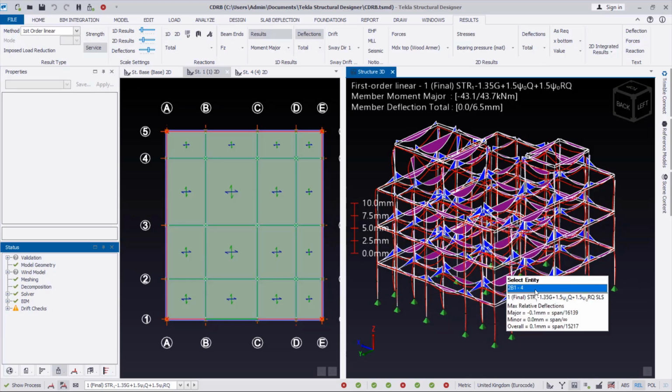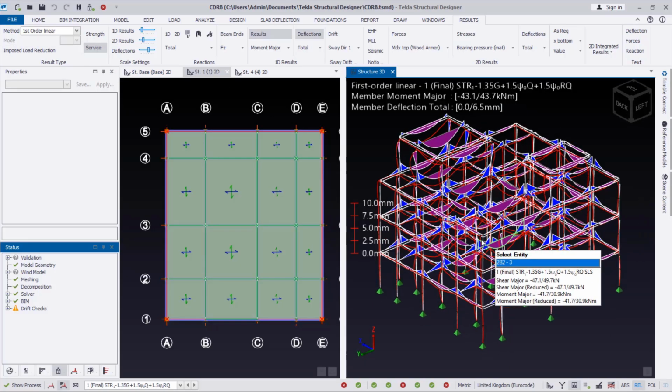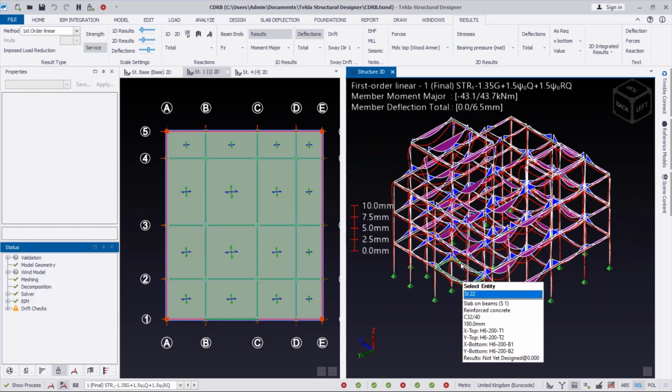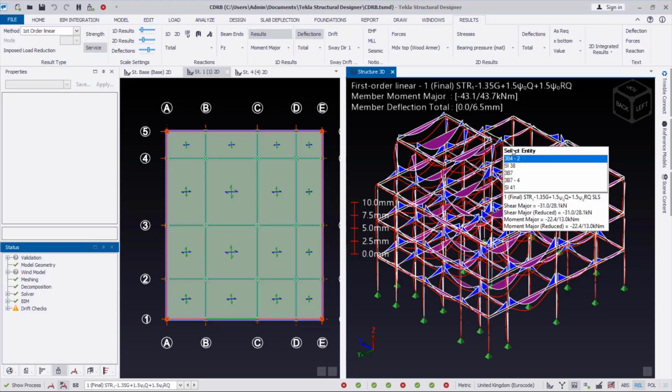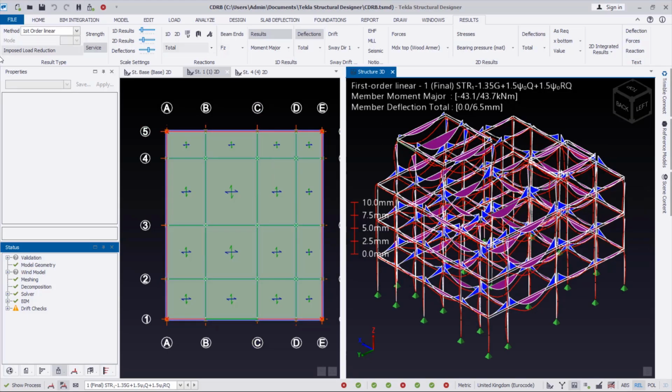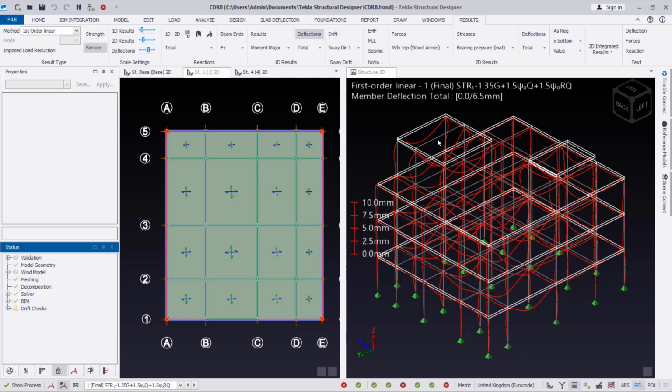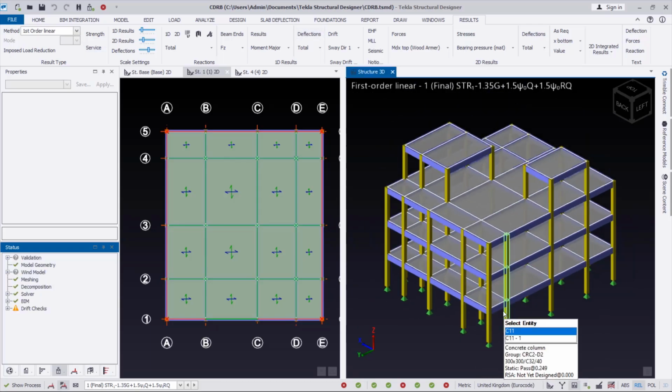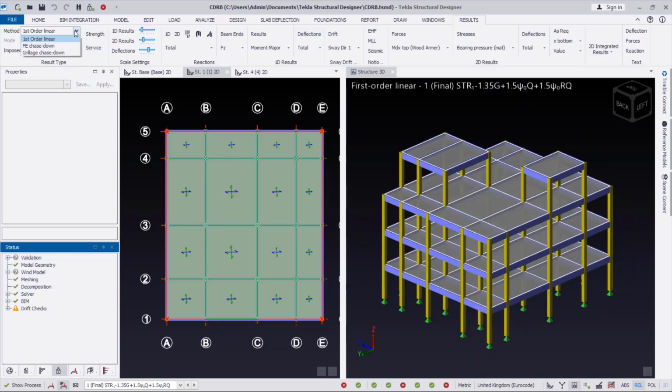Okay, so after which you can also view the slab or the finite element plate. So for you to view that, you need to activate the finite element in the method of analysis provision. Get rid of this as well to get back to the model, just like this. So come to these provisions and then click on the FE tester.